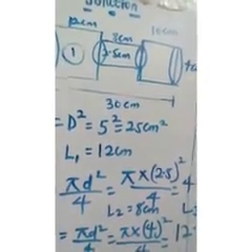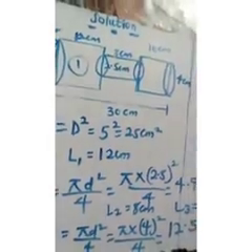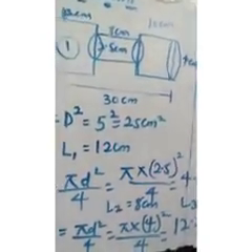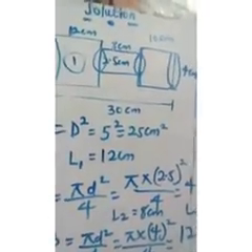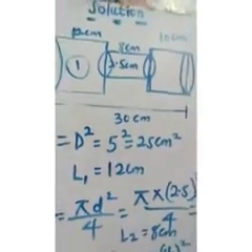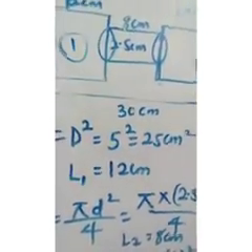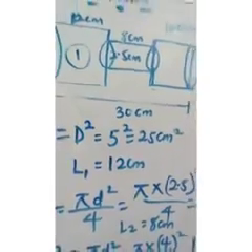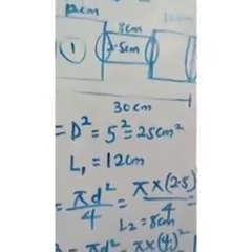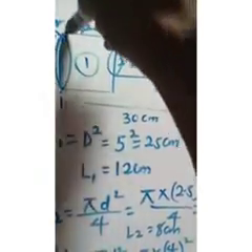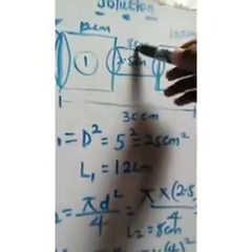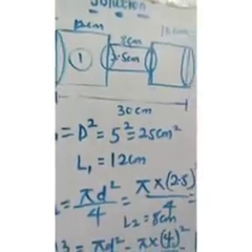And don't forget L3 is also equal to 10 centimeter. So therefore, you can find out that for axial load and stress and strain, the smallest stress will always occur at the longest length. By default, this will give us the smallest stress because it has the longest length, and this will give us the biggest stress. But let's show it first.